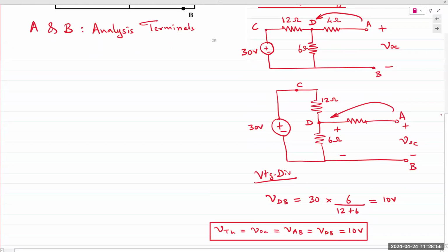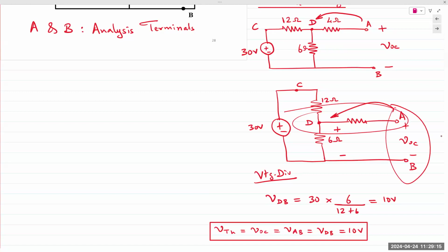When I redraw the circuit, I can redraw it in a rush, that's fine. But then I just need to reflect back and think, okay, node A and B, is anything connected between A and B? Then I look back at my redrawing, A and B has nothing, no. Between A and D, I have 4 ohms. I need to make sure I have 4 ohms between A and D, and so on and so forth.